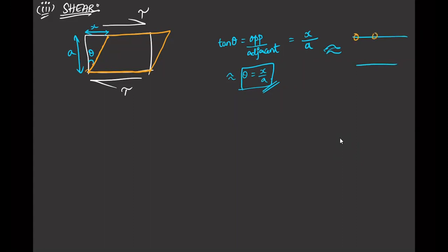For any deformation, for plastic deformation especially, the shear forces will help the plane of atoms to move with respect to the bottom plane of atoms. So shear displacement is one important term which we'll discuss in the full course, where we'll be discussing all the metallurgical fundamentals.